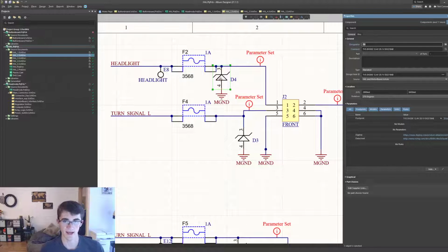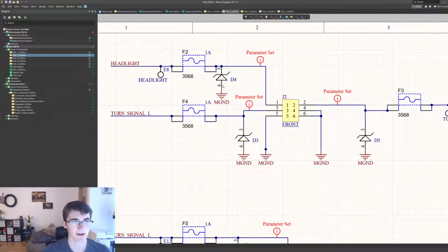video, we have a 12.4 volt TVS diode that'll break down after 12 volts. At this point, it'd be 12.4 volts. So that if there's ever a jump in that output voltage, since this is directly coming from the power board and it isn't getting through that power circuit in 5 volts, we want to have a TVS diode here. If there's a voltage spike, it will immediately shunt down to ground instead of going out the board and damaging either our horn or our light systems.